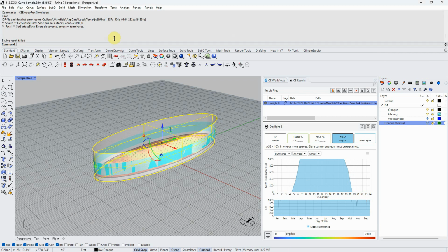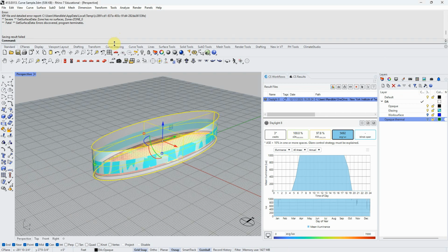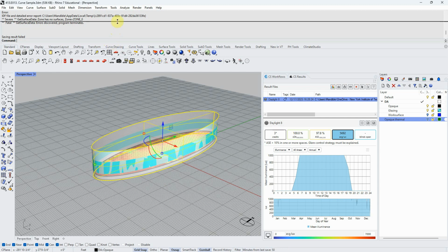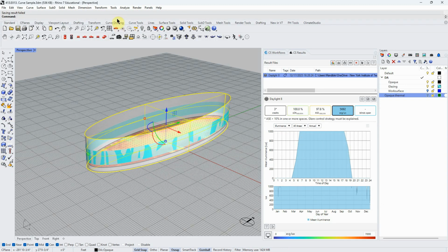services. So, by the way, if you get that kind of a glitch where you try to run a thermal analysis and it just blinks on and off really quickly, it's not that it's not working, it did work, just very quickly, and you can pull down and look at these command lines up here. Sometimes there'll be a lot of them, and sometimes you can solve the problem just using your common sense.